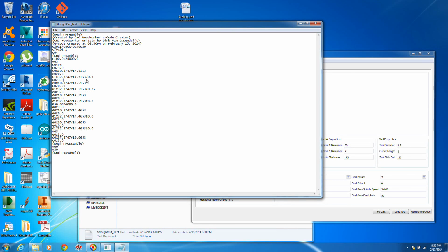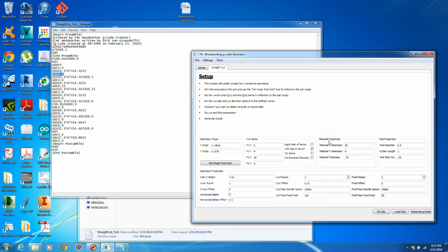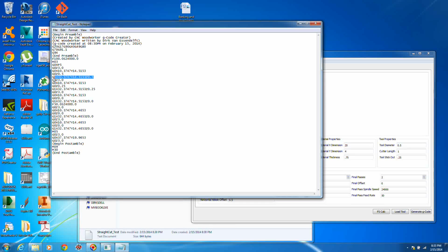Sorry again, guys, but it's good that I'm finding these things as I go through. I haven't actually run... Oh, no, actually, that's right. Because we chose to do cut passes 3, and we're starting with a material thickness of 0.5, the first pass should be at 0.5. Okay, so we'll do our feed from... We should be going from right to left, which is lower than this.